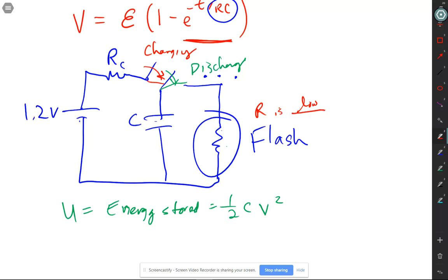Well, one idea people have is let's replace the batteries in our phones. Batteries are providing energy that they have stored in a chemical reaction. Let's replace those with capacitors. Let's make a supercapacitor that will store the same amount of energy, but with the capacitor, you can charge it really quickly. You just have to have a really small resistance for the input side, and you can charge it quickly because you have that RC time constant. Sounds great, right? Except there's the downside.